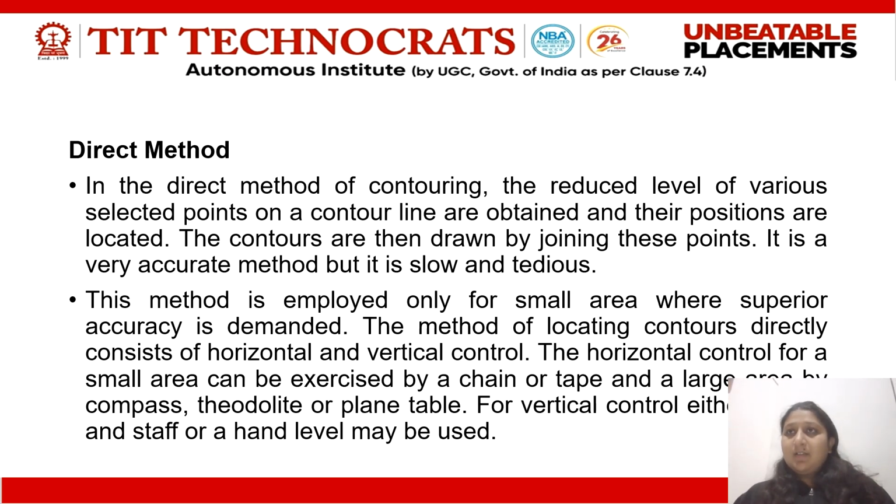Here, as I've said, we will go on the field, on the site, and perform all the tasks. Hence, for measuring the horizontal distances, we may use a chain or tape, and for a large area, I'll use a compass, theodolite, or plane table survey method. And for the vertical control, a staff or hand level may be used.